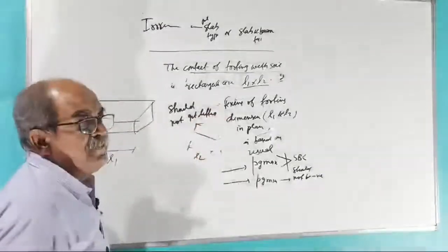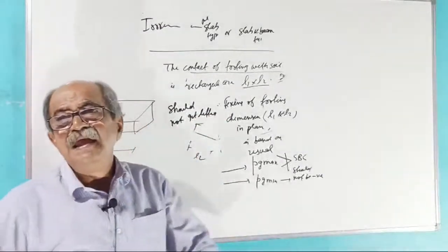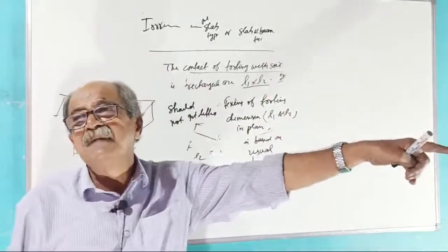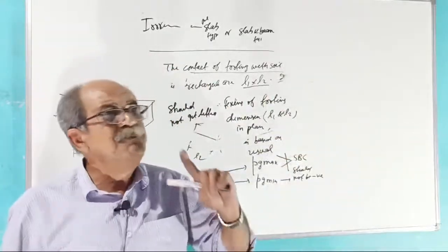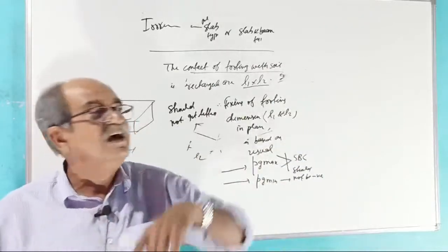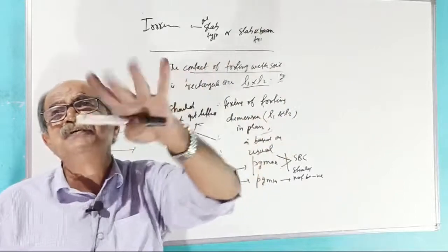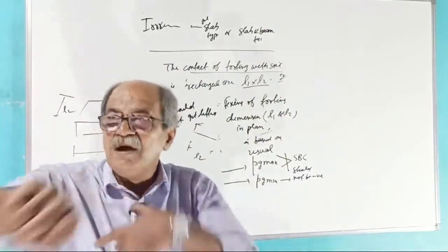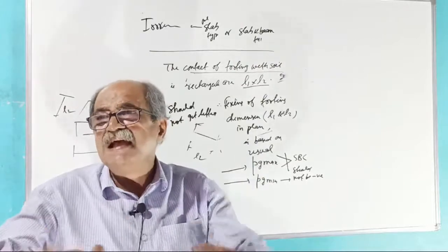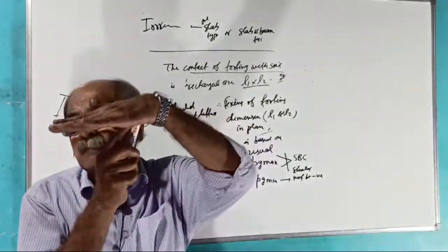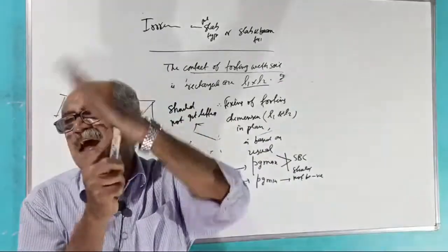Here, lifting is prevented if the minimum pressure is positive. In ETABS and SAFE, lifting is prevented if minimum pressure is negative. Here you do not want negative pressure. There you do not want positive pressure. And once again, if you go to STAAD Pro, reverse. STAAD Pro is like our class because our sign is pressure, compression positive, tension negative.